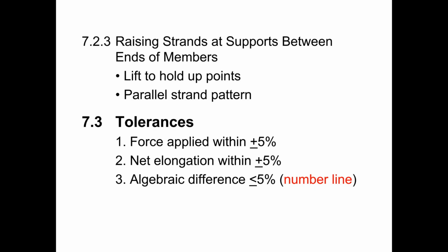All right, so let's talk a little bit about tolerances. Just as a reminder, for the tensioning tolerances for pre-stressing, we have 3 questions that we have to ask in order to determine whether or not a strand has been tensioned within tolerance. The first question is, was the applied force within plus or minus 5% of the required force?